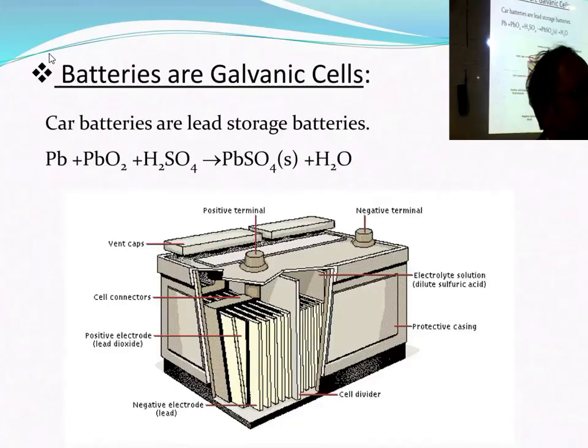There are two types of plates. One is lead plate. And these lead plates are made by casting. Casting means dhalai. You have heard the name cast iron, so it is also casted. That's why cast iron. So here these lead plates are casted. And it's like a grid, not a flat sheet, like a wire mesh or net type of thing. Lead plates are made like a grid.